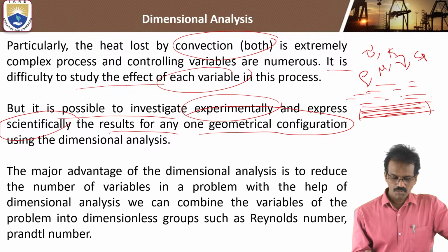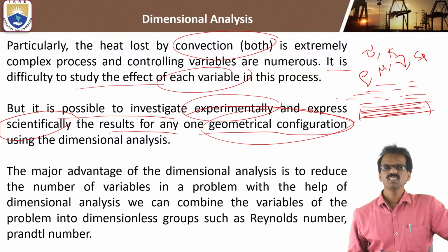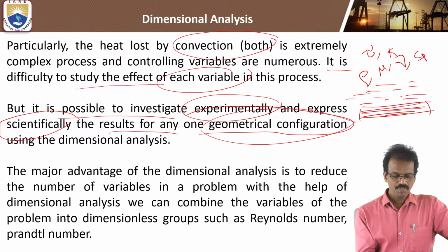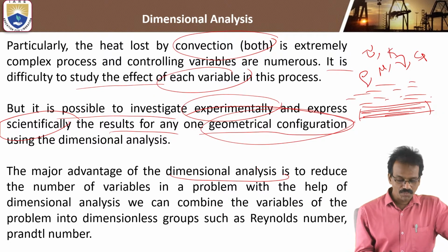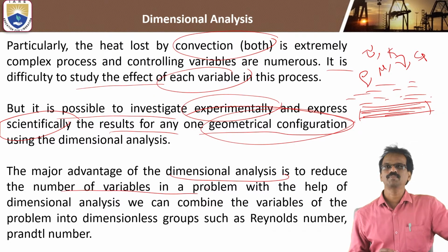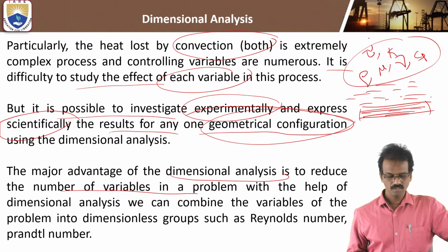So by using the dimensional analysis, we prepare some geometrical configurations. That is important. The major advantage of the dimensional analysis is to reduce the number of variables in a problem. It means we can combine all the variables into some dimensionless groups.